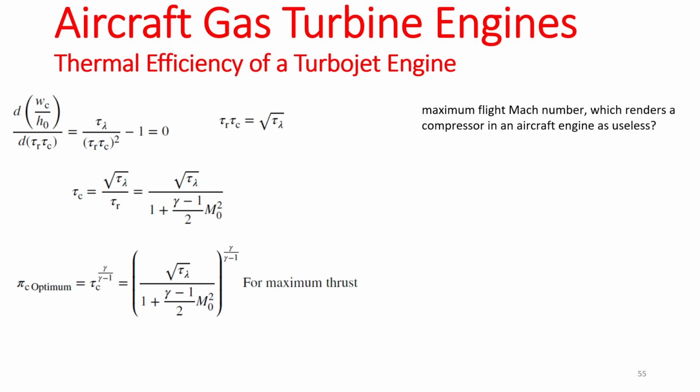You can do it at 0.9. You can do it at 0.8. The only difference is going to be that going into the combustor, you're not going to have the necessary pressure. Does it make sense? What does it mean? It means that your turbojet is not going to run, or your jet is not going to run as an ideal case, which already is not happening. Does it make sense? Okay, so that's not an important parameter. I don't want to say that's not an important parameter, but we'll get there. Hopefully, if you have enough time.